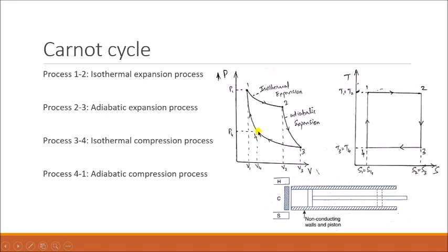So the piston again further starts compressing the gas. That is what is plotted in the PV diagram, process 4 to 1. During this process, again the pressure increases and the volume decreases, and finally it attains its initial state. Okay, so we say that a cycle has been completed. There are two different types of processes happening, isothermal expansion and compression, and adiabatic expansion and compression, and when all these processes are combined, we get what we call a thermodynamic cycle.